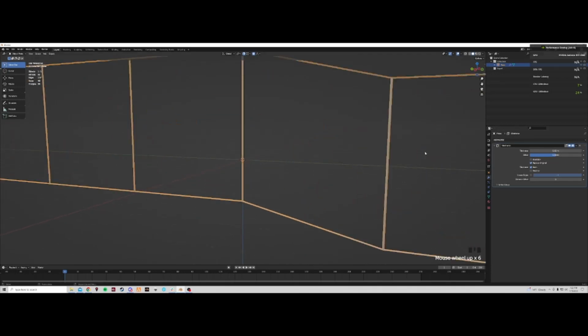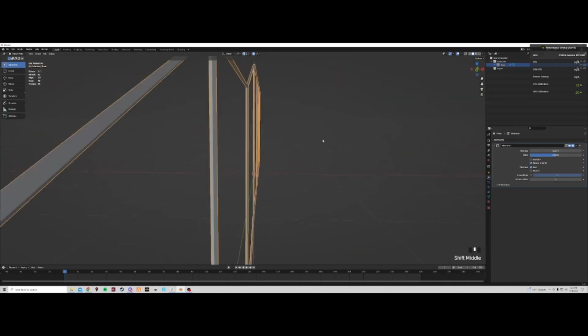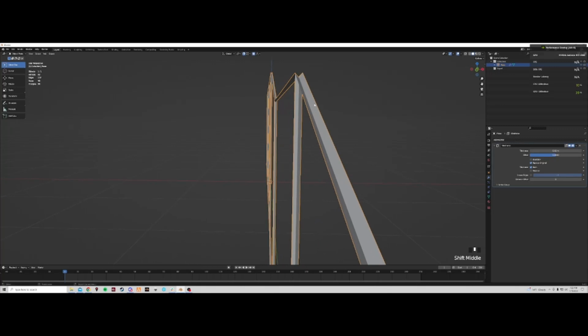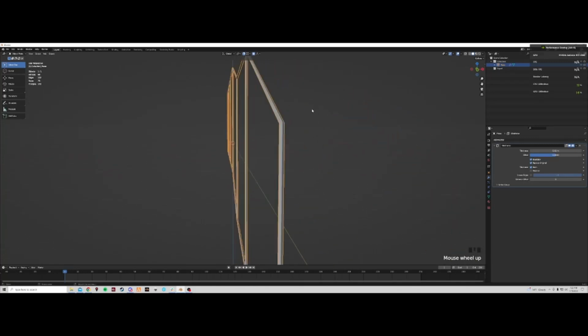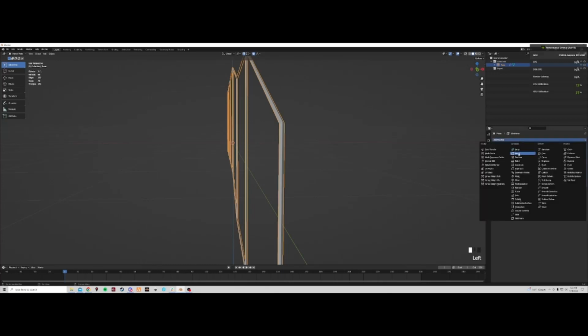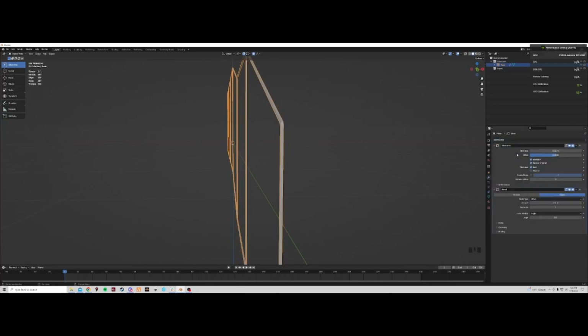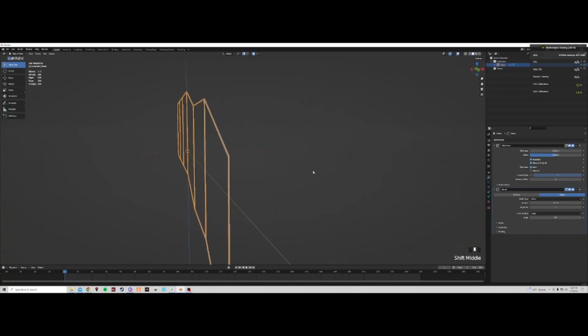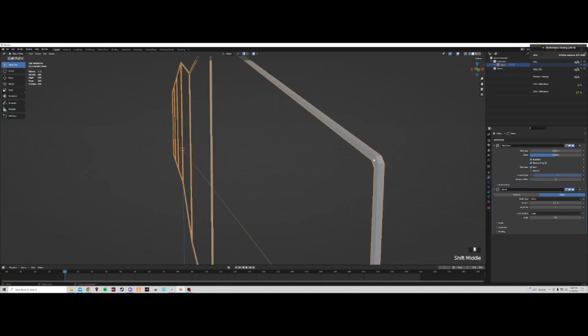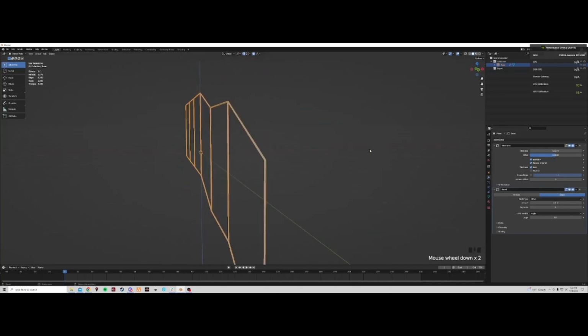If I look at this closely, you can see it's got like a weird kind of V shape going on for each frame. If I select boundary, it encloses that. Now it's got square shape, but it's diagonal. And I don't like that. So what I can do is also add another modifier called a bevel. And this will round it out. Now one bevel makes it square. If I start adding more, starts rounding it out.